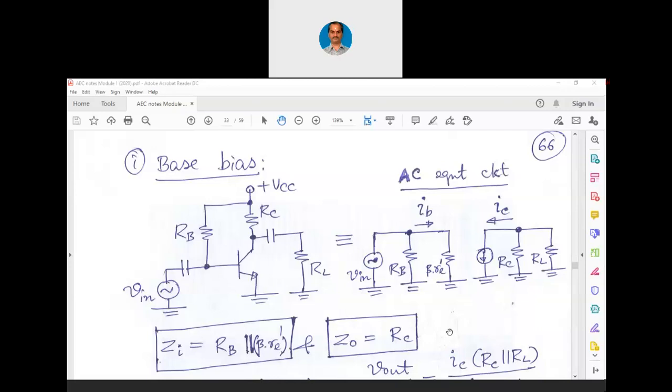If a signal is coming from a satellite, think about this V in itself. This V in itself is coming from a satellite. And let us say the impedance of the amplifier is now 1 kilo ohms. This very weak signal, will it be able to drive that much current into the input impedance? No. What we want is for the amplifier to work independent of the power of the input signal. The power of the input signal should not be reduced because of the amplifier. Okay, that is the basic idea here.